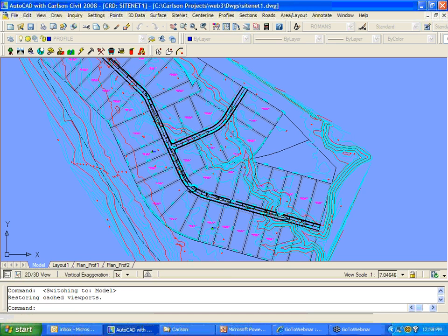In the second sheet, can the plan view be rotated to make the alignment exactly parallel to the bottom of the sheet? To make the alignment exactly parallel. Well, it's just a D-view twist is all we're using. So you could certainly D-view twist it.